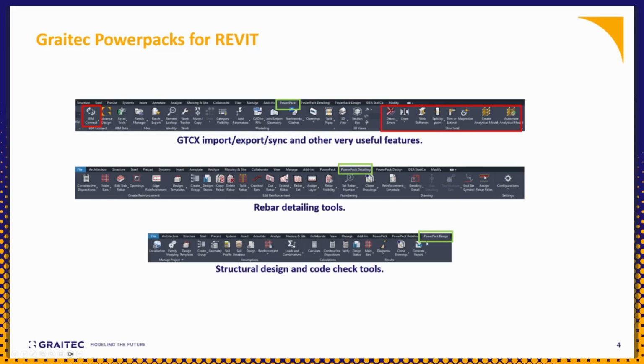And the other tool, PowerPack Design, is based on the internal loads. It's going to do the design and rebar placement based on the codes that you are using. We have the localization here, so different country codes that you can select, and based on the forces imported from Advanced Design, in this tool, PowerPack Design, we can perform our rebar detailing based on internal forces, FEM forces coming from Advanced Design.